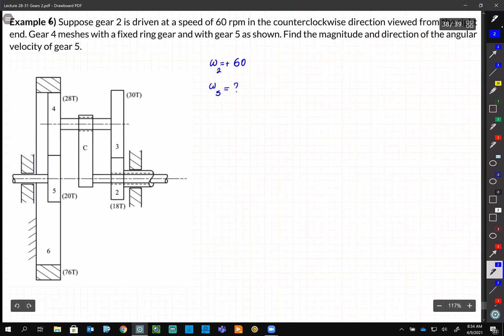Okay? Look at 6. 6 is an internal gear, right? It's a large gear. In this picture, we just show the cross section of these gears. And this carrier is rotating 3 and 4 around this 5. And the ring is being fixed. See, this is the sign that tells us that the ring is being fixed.